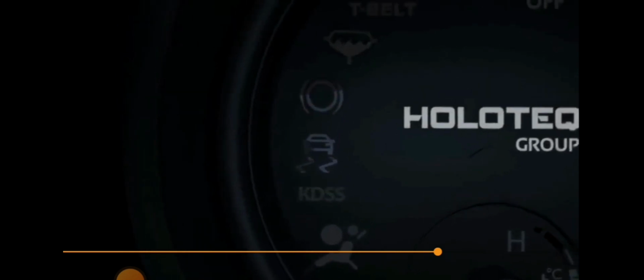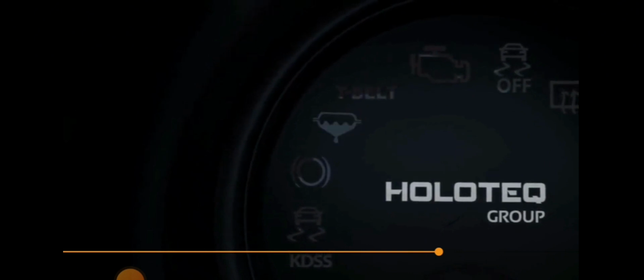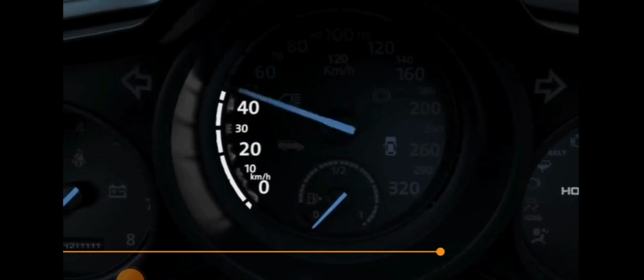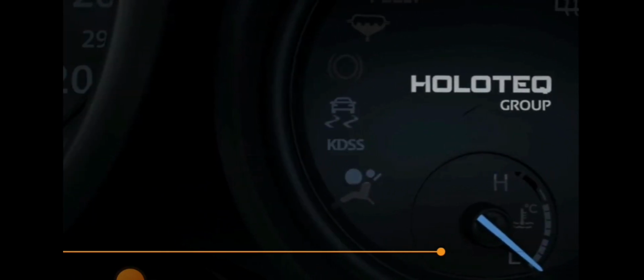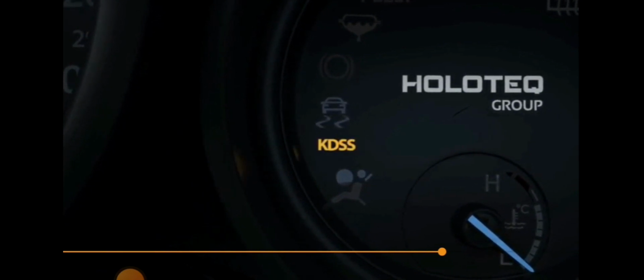Fuel strainer indicator. The strainer should be replaced as soon as possible. Maximum speed limit warning indicator. Reduce the speed. Kinetic Dynamic Suspension System, KDSS, indicator. There is a fault in the system. Refer to the maintenance workshop as soon as possible.